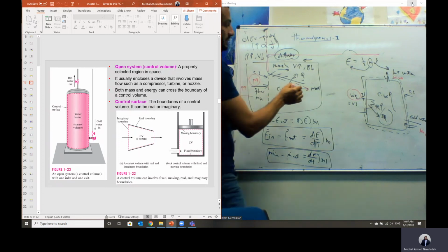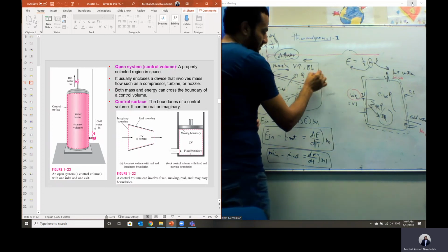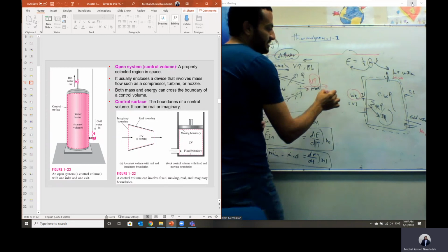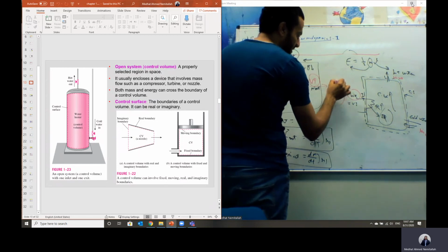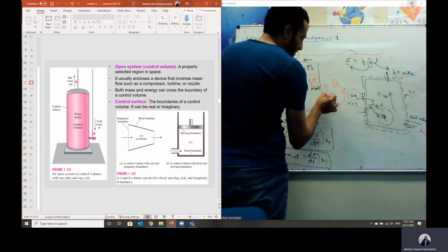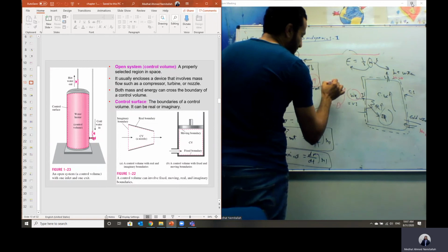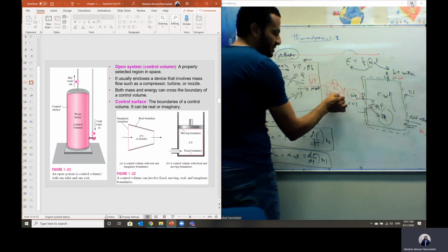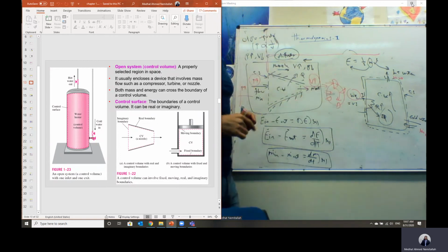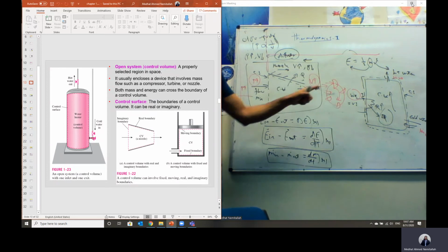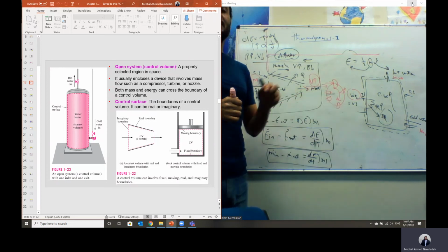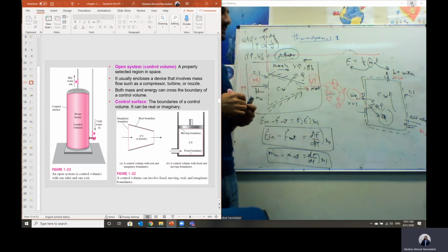Then we can convert it into kinetic energy, a high velocity jet. And then we have a hydraulic turbine wheel with buckets. This high velocity jet hits the bucket, then the wheel will be driven. Then we can generate shaft power, so that we can connect this hydraulic turbine to an electric generator to generate electrical power. And this is the idea of the hydraulic turbine.